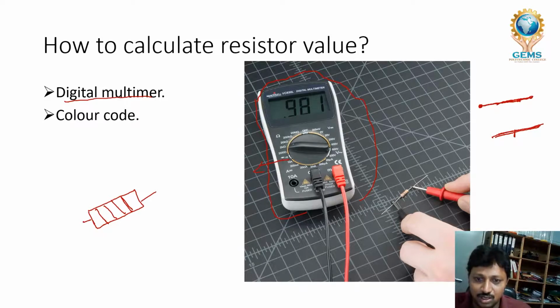So you just put this knob here, bring it here. Two points are there. Just connect one here and this one here, right? So what happens? The beep sound will come. So it means there is no breakage. If the beep sound does not come, it means somewhere inside the wire, the copper wire is broken. It means there is no continuity, so it doesn't make a beep sound.